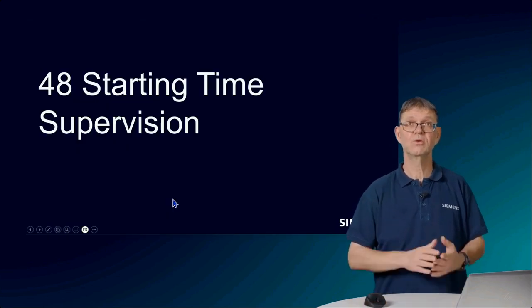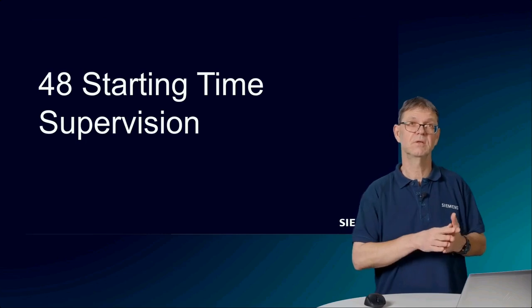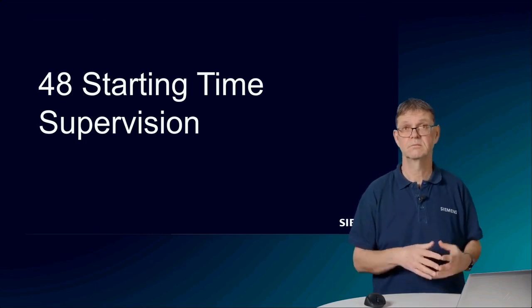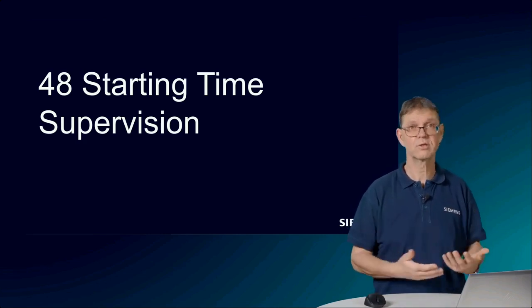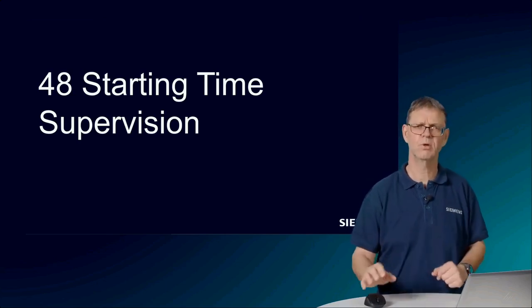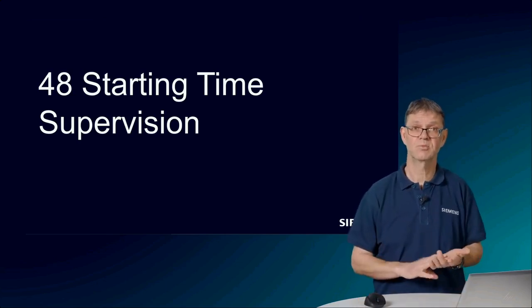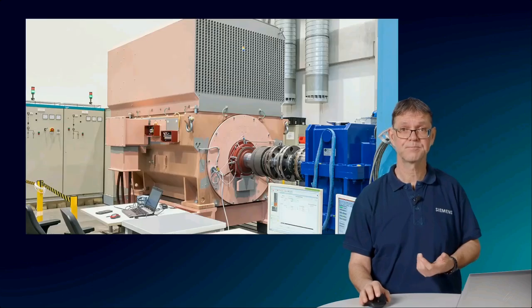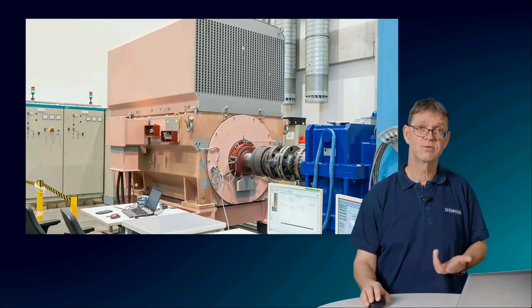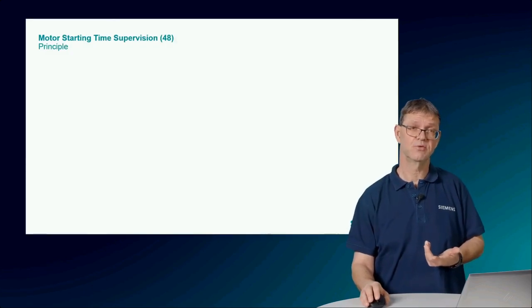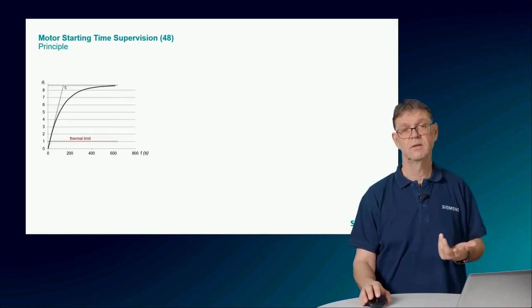Okay, let's go to the second function for the rotor overload protection or temperature monitoring. It's the starting time supervision, ANSI code 48. Here the principle is the following.